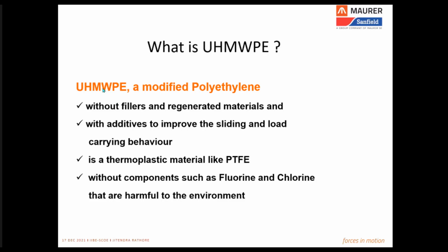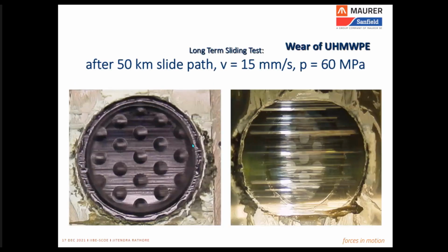The generic material polyethylene is modified with certain special fillers and materials to get the desired properties, and additives were added to improve the sliding and load carrying behavior. Since it is also a thermoplastic material like PTFE, it has similar properties, but altogether a different level of performance as compared to PTFE.